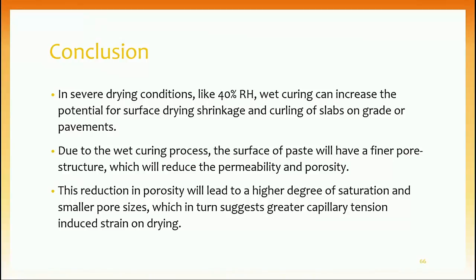Due to the wet curing process, we have a refinement in the pore structure, which can reduce the permeability and porosity. This reduction in the pore sizes can cause a higher degree of saturation after curing longer, and it also produces smaller pore sizes, which in turn suggests greater capillary tension and induces a strain upon drying.